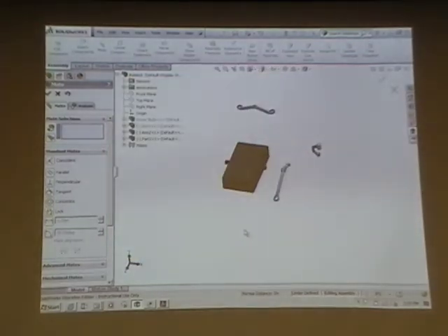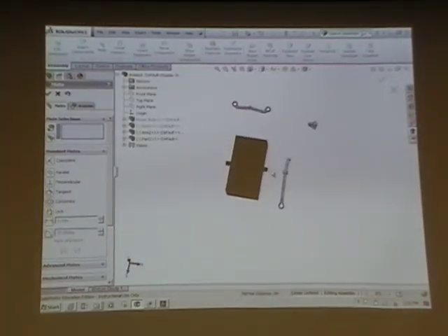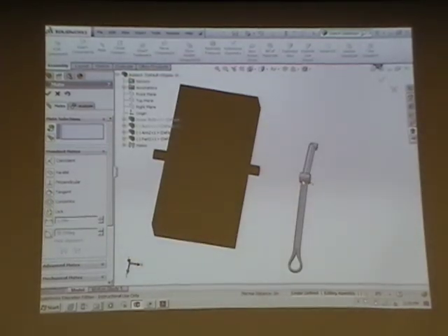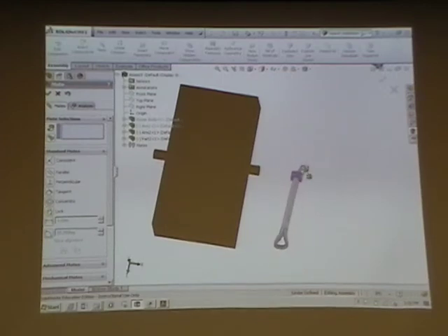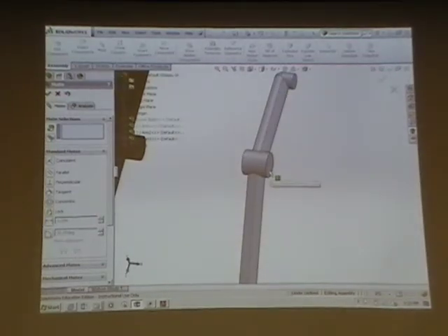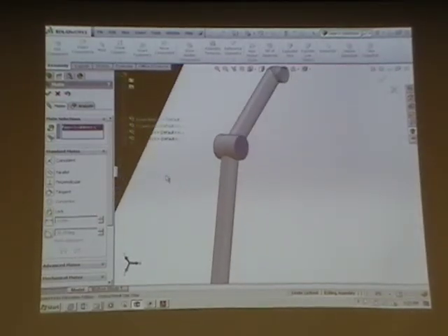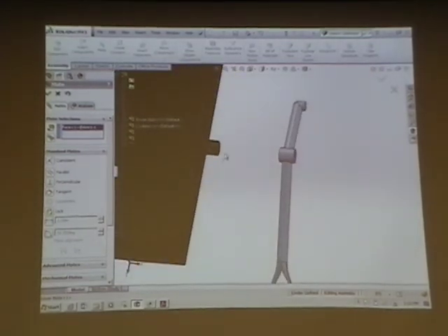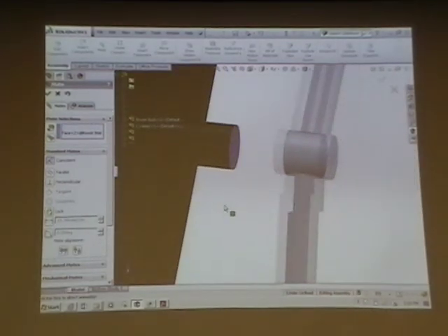Click the check mark. Okay, so those axes now are going to be coincident. And if I click and drag this, I can still change its rotation, and I can slide it back and forth, but I can't misalign those two axes. Those are always going to be coincident. So the other thing I want to do is make this face here coincident with the corresponding circular face of that knob.